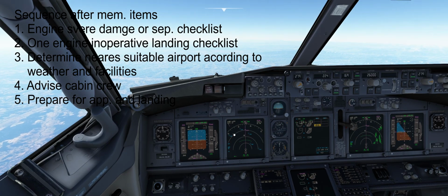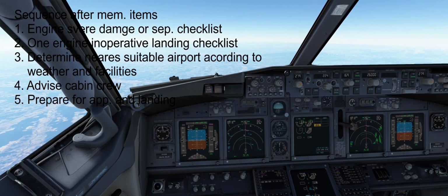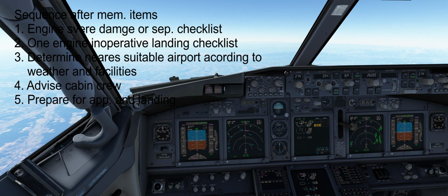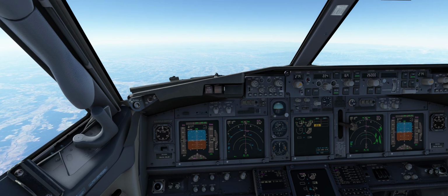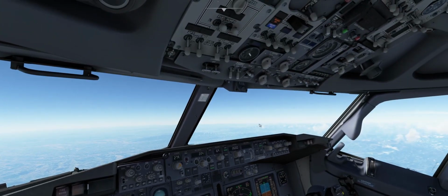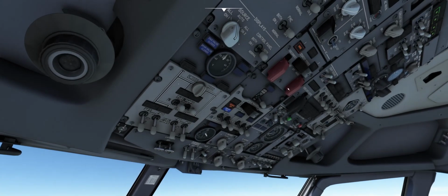But please, once again, aviate, navigate, communicate, do the checklist. So don't hurry with these things. You have plenty of time. You have all of your time. And now if you are going through the QRH, I will not show you right now, but the QRH says that we have to start the APU. This is the first point.